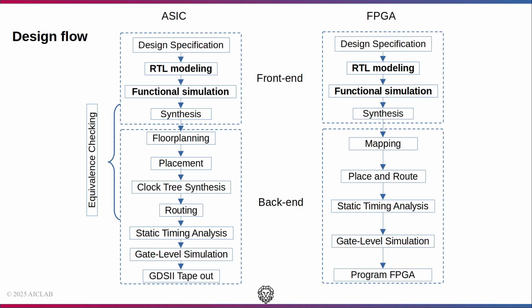Static timing analysis or STA is then performed. This process checks the timing of digital circuit without doing the SPICE simulation. It uses timing information extracted from a standard cell library and parasitic information derived from wire load model and physical libraries to identify potential timing violation.